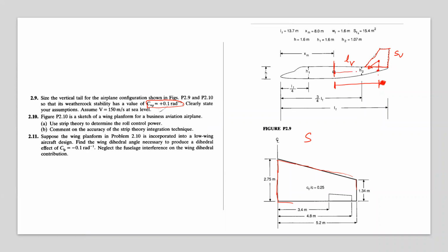So you can take an axis like this, and this axis passes through the CG and is along the fuselage center line. Now, this distance multiplied by this force gives a moment like this, and that moment is actually the roll moment. Can you recognize that? Yes, sir.